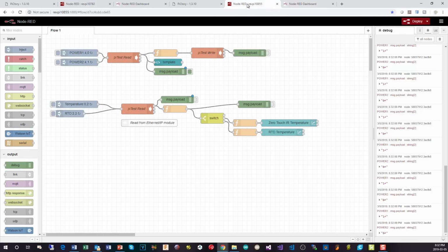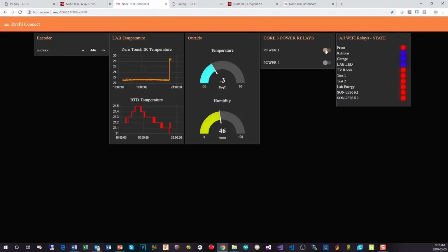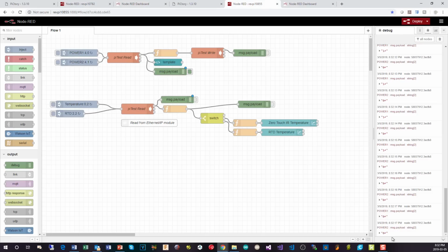Sorry, showing you the display there. Here now you've got a 1 and a 0 coming out, and if I turn off the other bit, you'll see that there's a 0, 0 now coming out. So you can see that we're passing this data across using Modbus into a memory location via the Ethernet IP, and here we are picking up that memory location and bringing it through to the Node-RED flows.